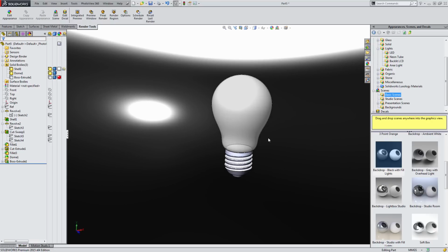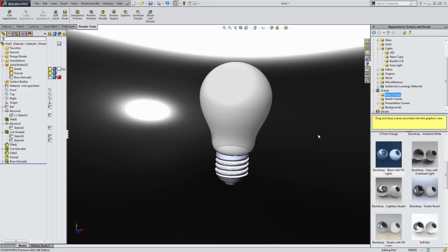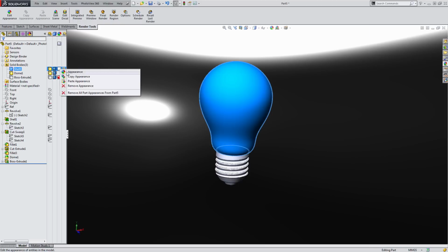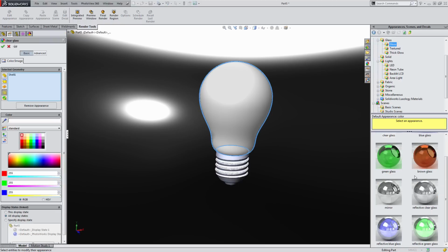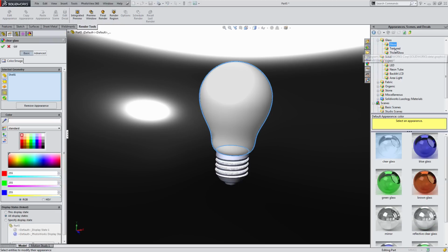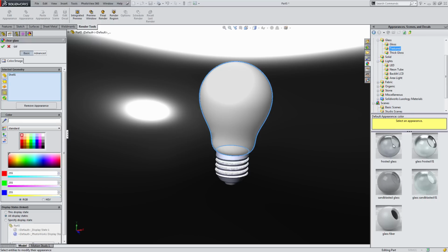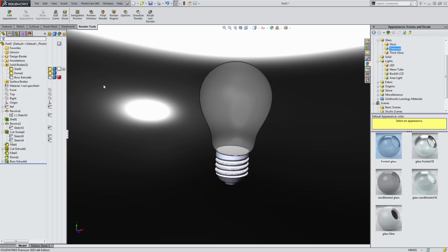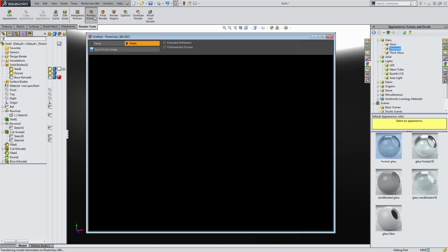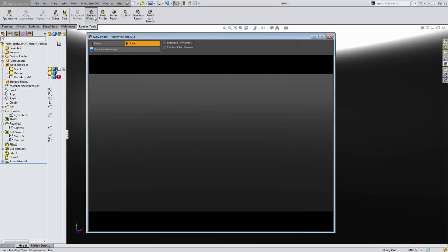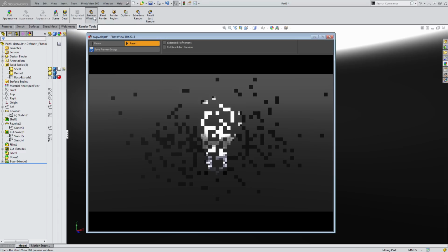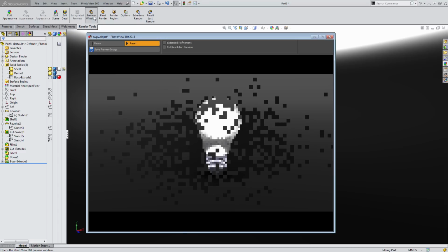We can obviously spend a lot of time manipulating the glass material, manipulating the light material, modifying these properties. And it can take you down a very deep hole of different things. Now, if you're actually looking at creating a light bulb for aesthetics, this is perfect for you. If you're actually trying to create it for emitting light on something, it's probably too much time invested because it takes a lot of extra time inside of renders to do that sort of thing. But we have a realistic looking light bulb, and hope you learned a few things in the modeling process of how we were creating that geometry and apply that to your specific models.